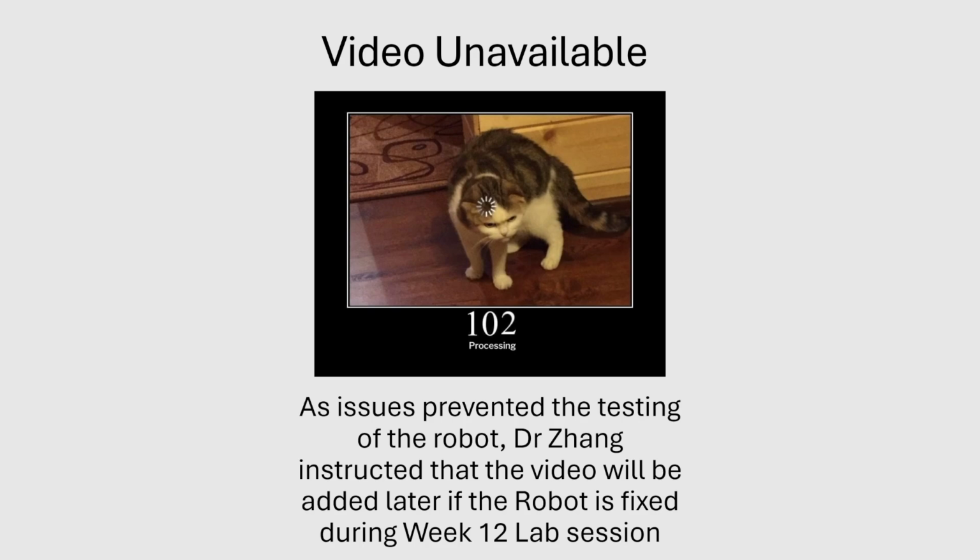As the robot moves through the space, we would expect to see a map gradually form in RViz. Areas observed by the laser appear as free or occupied, depending on whether the beam is encountering open space or walls and obstacles. Meanwhile, the robot's pose estimate becomes more accurate as more of the environment is explored. The outcome of this task, even though we were unable to record a video, is a complete representation of the virtual room once we have driven around all the boundaries. It also helps illustrate why proper exploration matters. Without steering the robot into every corner, gaps will remain in the map.